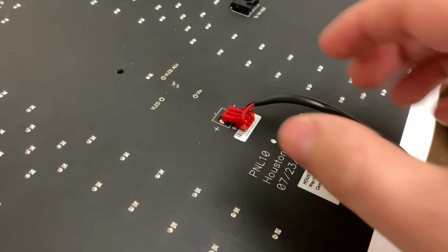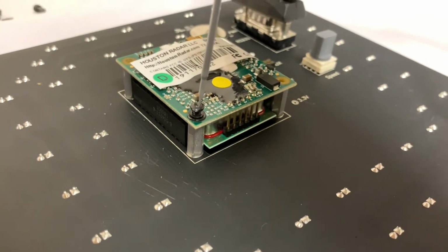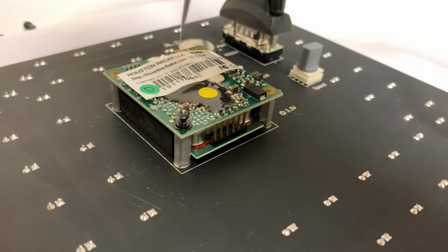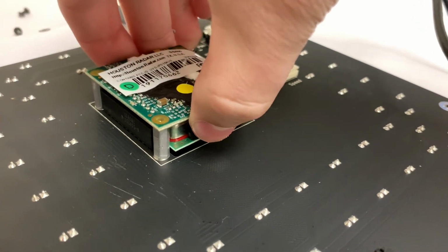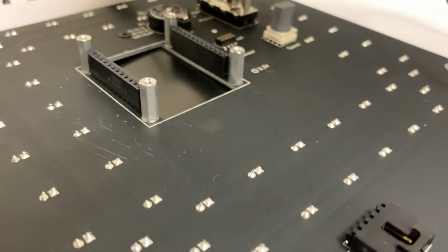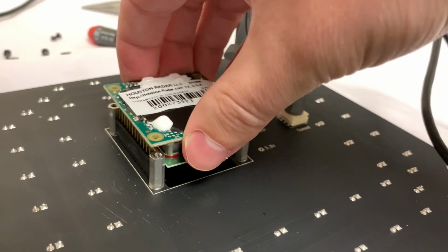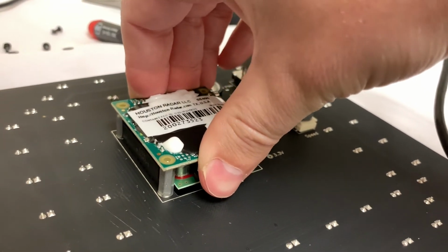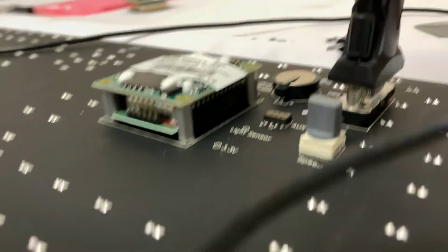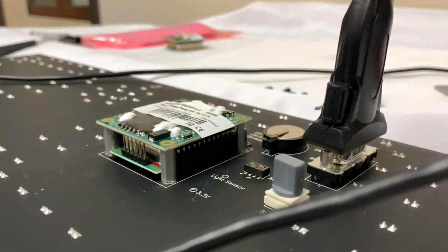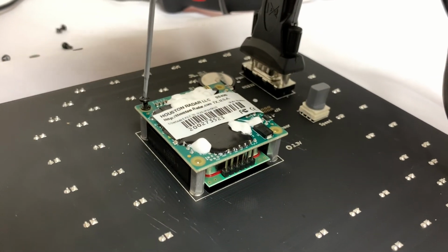If you are replacing a radar, remove power before touching any of the components. Once power has been removed, unscrew the 4 mounting screws around the radar board. Then carefully rock the radar board back and forth to release the pin connections and remove the board. Carefully place the new board in a similar manner, making sure not to bend any pins and checking both sides for solid and complete placement. Then secure the mounting screws and return power to the board.